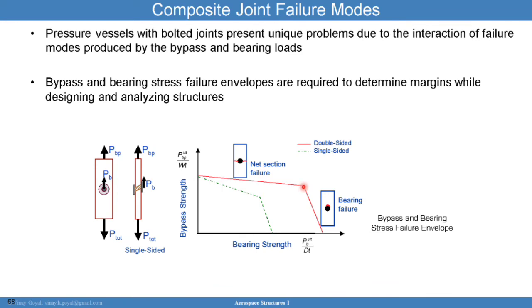And there's a point at which, if the bearing stress is too high, the mechanism switches to bearing strength failure. In those cases, what you get is a compression failure just ahead of the hole, which causes hole elongation. And that hole elongation is going to cause potential problems: excessive bending in the joint, loss of stiffness, and other consequential failure modes that could be a problem.